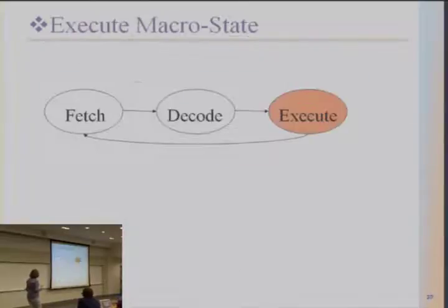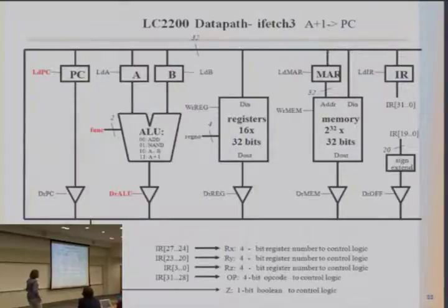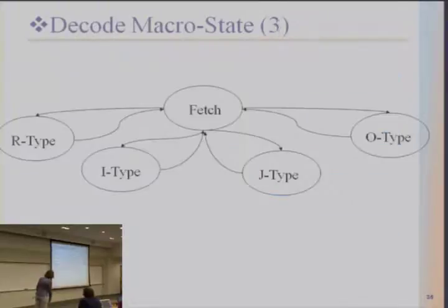If you look at it from the bus perspective, if I have to read only 4 bits from the instruction register, and I don't have a way of passing only 4 of them, I would have to load here all 32, and then I would need some logic to determine which 4 I need, which is pretty much exactly what we did with this multiplexer.